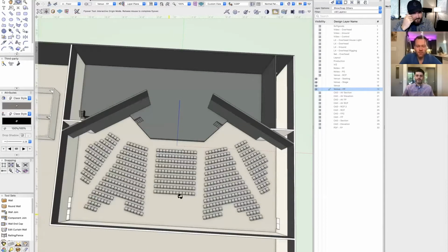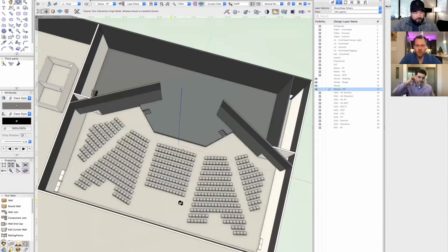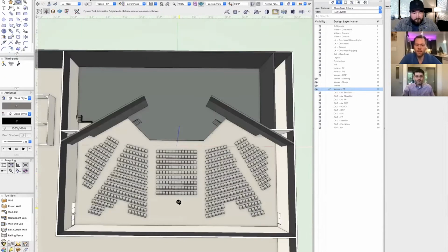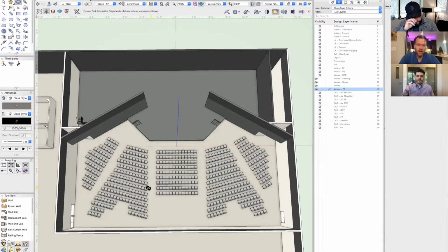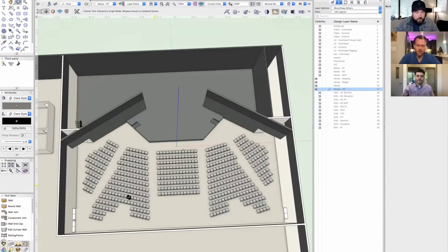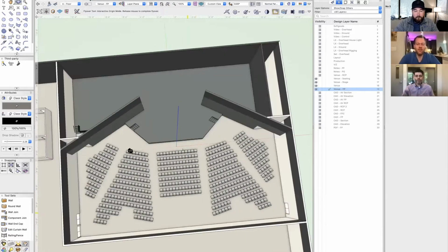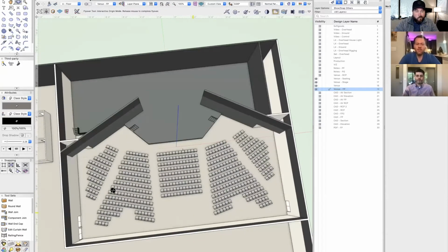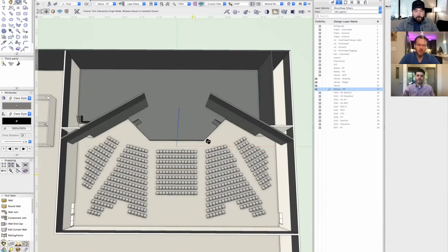All right, so we've got the model of the rooms, kind of basic shape, which I think is a good start. And anything after this, we'll probably want to talk to the client for sure. Once an architect's involved, the other big thing the architect is responsible for is exit safety and local municipal codes. I put in some seats just to give us some scale and spacing here. I have no idea what their code is as far as aisle widths and row counts. So we'll let the client know as we go, hey, this is an idea of your seats, the architect is going to make this call. They're the ones whose names and stamps are on it, and they're responsible for it.